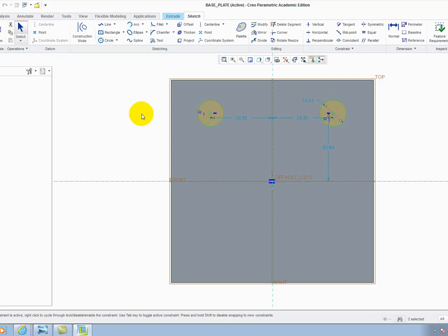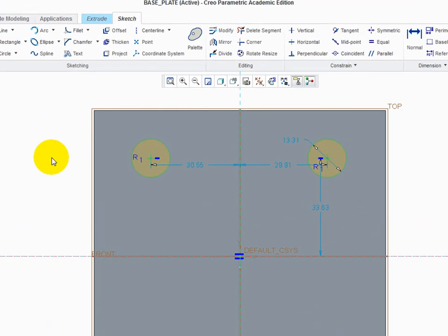I've just realised I want the 2 circles to be symmetric around the vertical reference plane as well. So I'm going to go and put another center line in. This will help me to make them symmetric. Go back to center line, select it, let it snap to the vertical reference line, left click once. Bring it down and round and let it snap to being vertical as well.